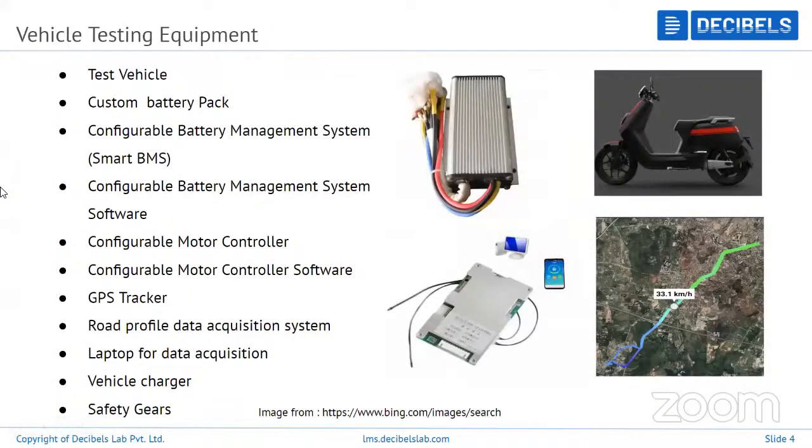Yeah. So when you talk about a GPS tracker, why? Because to get complete vehicle speed accuracy, when you compare with IC engines, you have an OBD scanner where you attain the vehicle speed, right? Sometimes a GPS tracker will be able to give you the speed at a higher frequency, maybe for milliseconds. This would help you in component designing for your acceleration test, or maybe certain difficult situations.